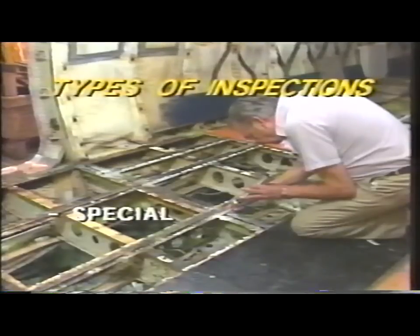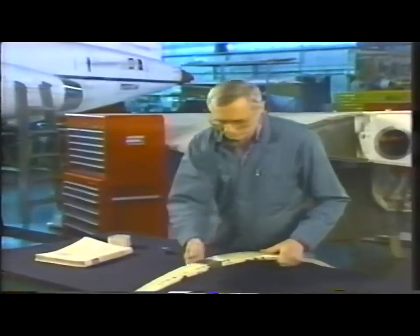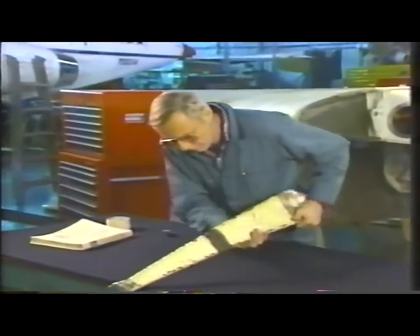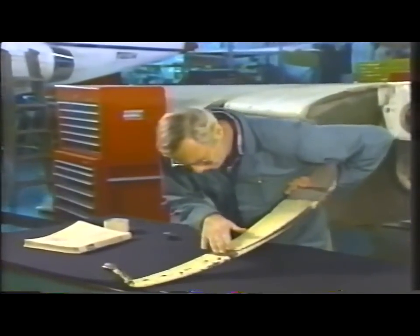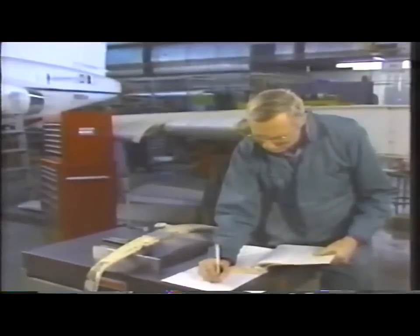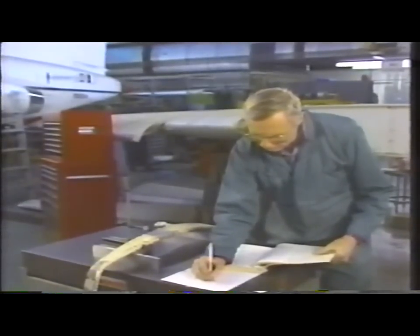Special corrosion inspections are required at each overhaul, routine inspection, or when required by an airworthiness directive or recommended by a manufacturer. When corrosion is found, the quality control inspector makes an evaluation to determine the extent and types of damage sustained, and then recommends a course of corrective action. The results of every corrosion inspection should then be recorded for later analysis.